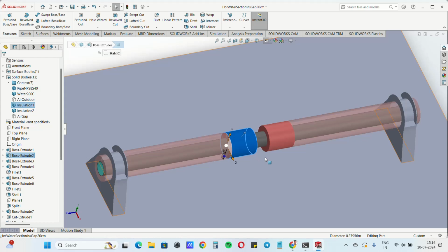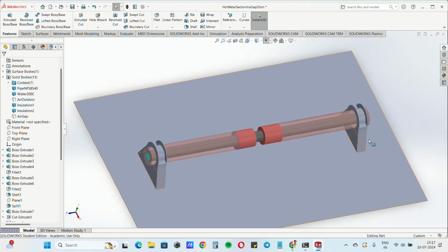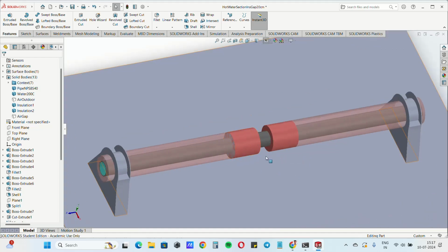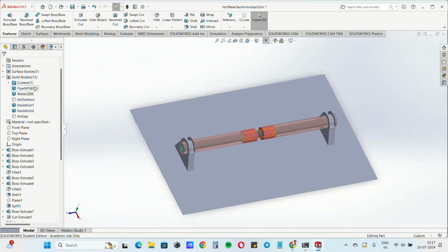So which means there is forced convection, and the scenario is you have a shutdown and the heat influx stops for some duration of time, as well as the flow stops, and during this period there will be a thermal cool down. What we have to do is to estimate how much the liquid inside the pipe would cool down for this duration of time. That's the context of the problem.